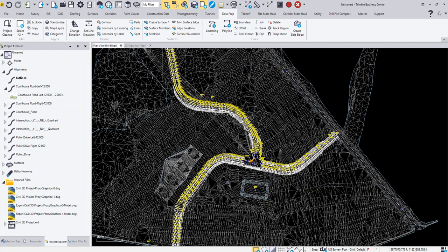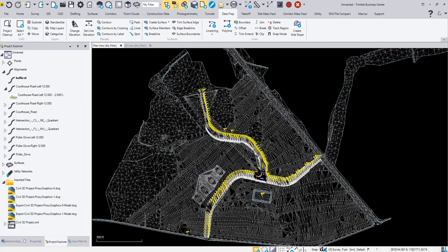All right, so this is the LandXML file. These are the results. The LandXML file export doesn't have any bearing on whether the drawing is set with Proxy Graphics 1 or 0. It's basically taking the Civil 3D objects, putting them into a generic format that any other program can read. So LandXML is kind of like, if you want to think of it as a CSV file for text data or point data, but it packages everything and other programs read it the way that it was designed in the original source program itself. Okay. So again, LandXML and Proxy Graphics are key when getting data from Civil 3D.